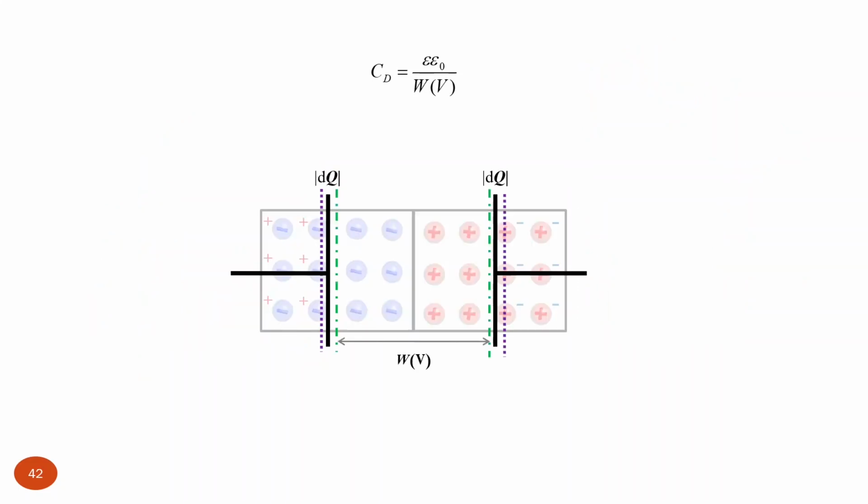That's why we can have an analogy between PN junction capacitance behavior and parallel plate capacitor behavior, because this small change of charges is what actually matters in terms of measuring capacitance, because capacitance is equal to Q divided by V, or in our case delta Q divided by delta V. This change of electric charge, associated with charging and discharging the PN junction capacitor and the parallel plate capacitor, will happen within these narrow layers at the edges of the PN junction.